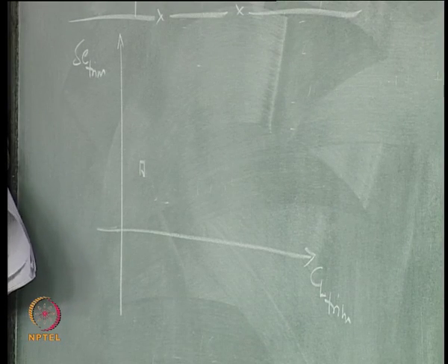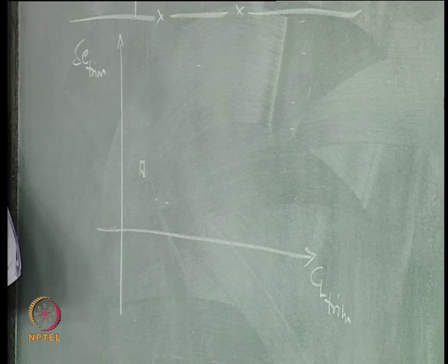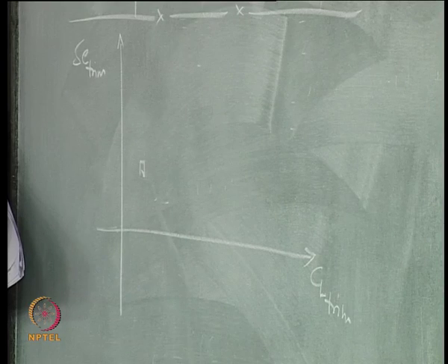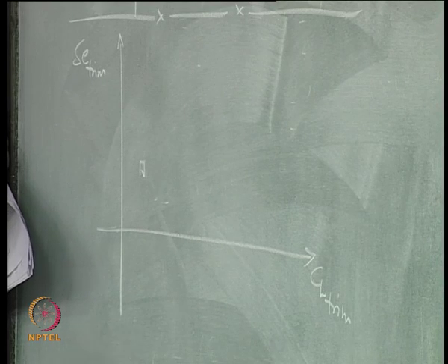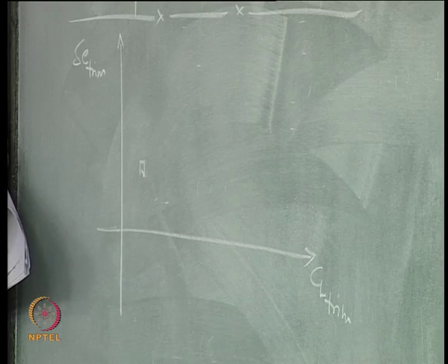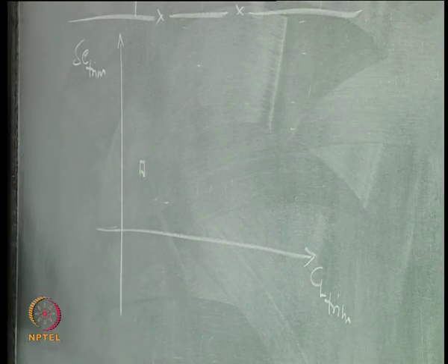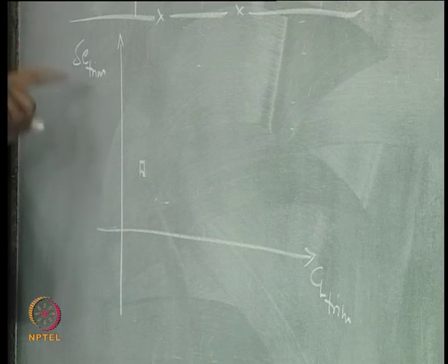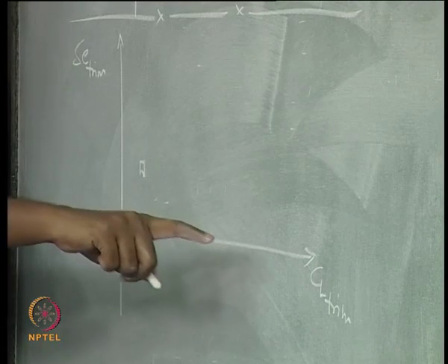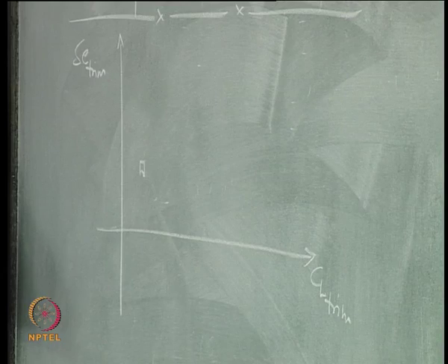one speed. Okay. So, one CG condition, CG is fixed, that Cm alpha is fixed, right, and now I am flying one velocity. So, I am at this delta E trim, this CL trim, change the speed.